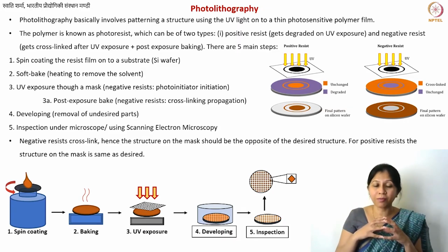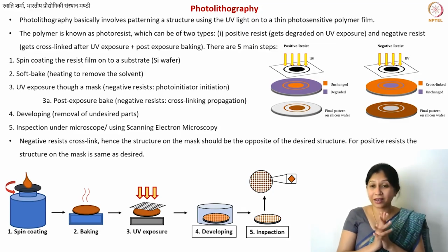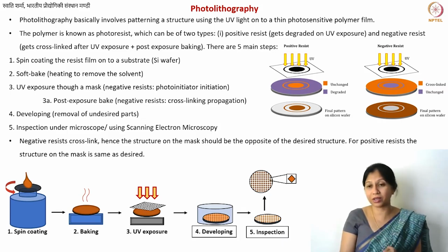Okay, so now what is the next step? You have a photoresist, you perform photolithography, you get some microscale structures, and now you take your entire silicon wafer or the pieces, put it inside the furnace, and heat it at 900. Now, why 900? There is one more important thing. Why don't we go to 3000 degrees? Why can't we make better carbon?